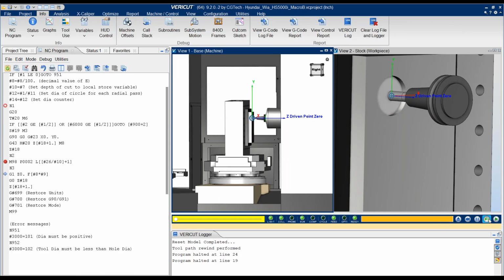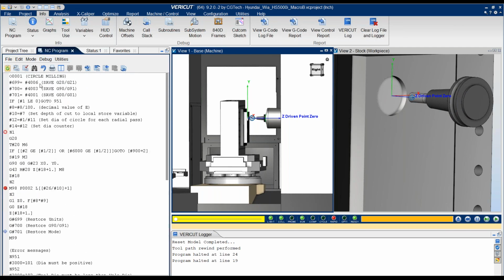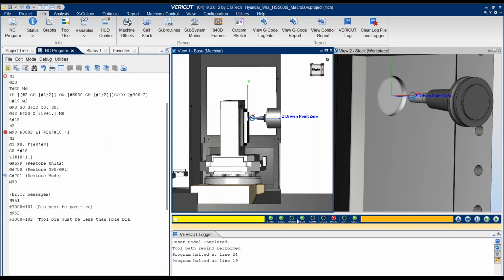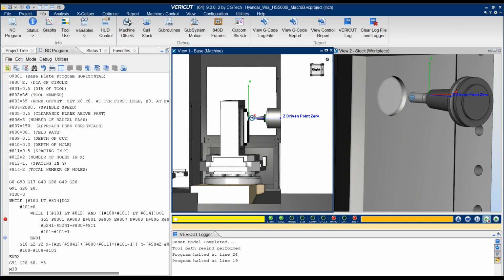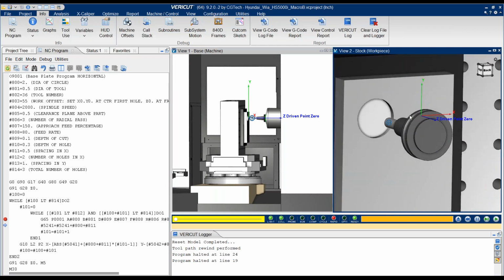Okay, now what we're going to do is step out, and you can see that at the beginning of this, we stored some system parameters, our mode and our feed mode, and we're restoring those before we jump back out of the subroutine. And then here, we're updating the actual G55 system variable offset. And inside VERICUT, you can see that it updated that value.